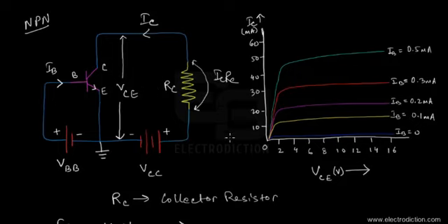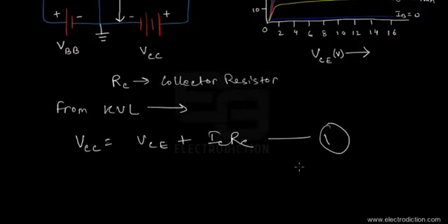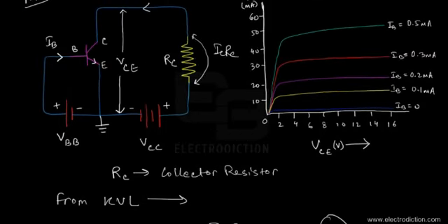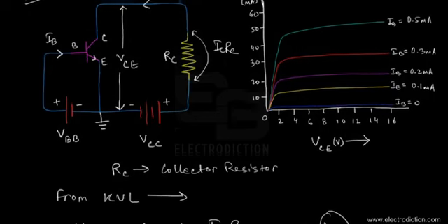If we take a look at this equation once again, we can understand that the voltage coming from the supply voltage source divides itself into two parts and distributes across the resistor and the BJT's collector and emitter terminals.